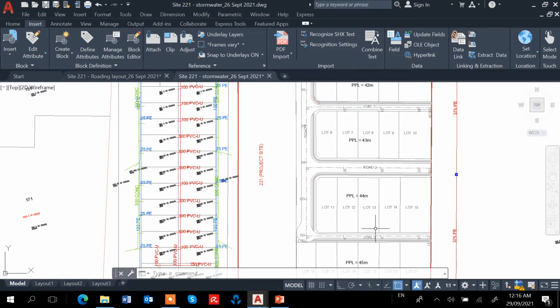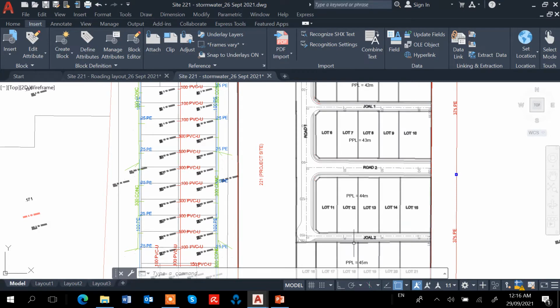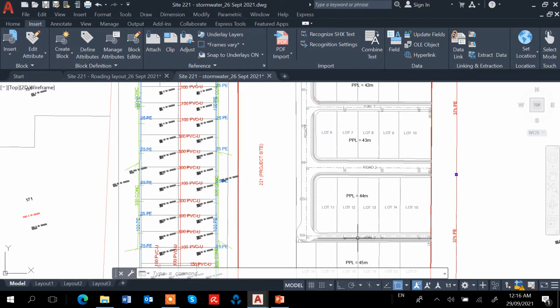I'm probably going to use a steeper slope. You could use this one. I can use a 1 in 200. Actually, I could use 1 in 300. Okay, 1 in 300. I think the Auckland Council bylaw mentions that the minimum gradient, minimum slope, is 1 in 1000.